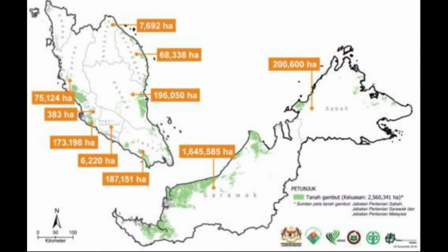Malaysian peat is a tropical peat. Sarawak has the largest peat land area in Malaysia, which is about 16,500 km² or 13% of the state, of which about 90% of the peat is more than 1 meter in depth. This peat has unique characteristics which make it significantly different from other peat.